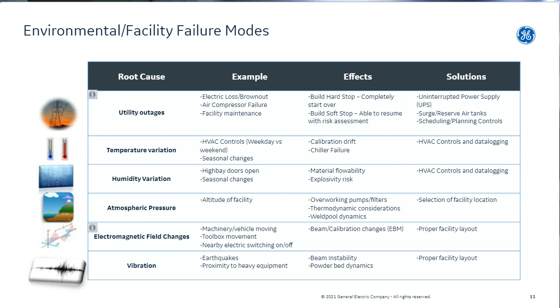But in these larger altitude changes, the pumps will perform differently. The cooling of the machine as well, where we've got a lot of heat being input with multiple kilowatt lasers or an electron gun, and you're trying to keep the machine in a nice steady state temperature. The air conditioning units for these machines will perform differently. They'll be cycling on and off more often. The heat doesn't dissipate as well in those thinner airs.